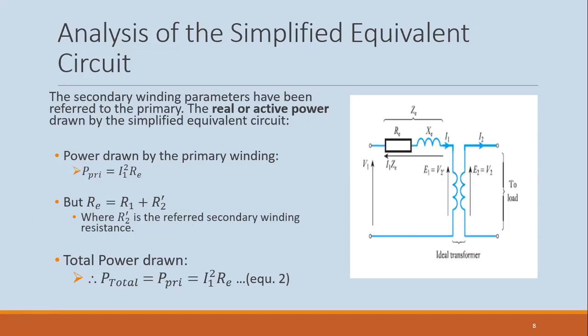Yes, sir. When a load comes on, you're going to have current flowing and you're going to have a voltage drop. What we have done is move the impedances from here and put them over here. So the voltage drop that we will be calculating is as if all the winding impedances are on the primary.